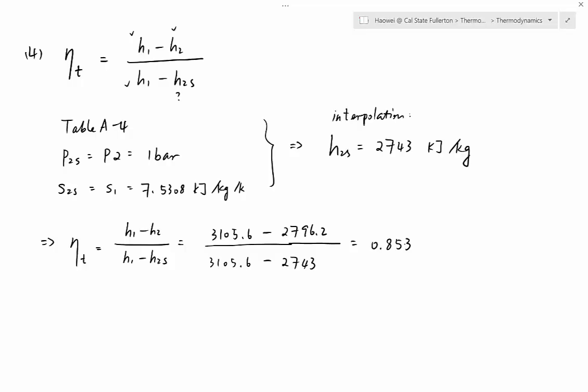So how come when it comes to the whole vapor power system, like the power plant, usually the efficiency is only 40%, which is very, very low, even though the turbine itself has a very high efficiency. The compressor also has a very high efficiency. The boiler is also high. The reason why the whole system has a relatively low efficiency is because of the condenser.